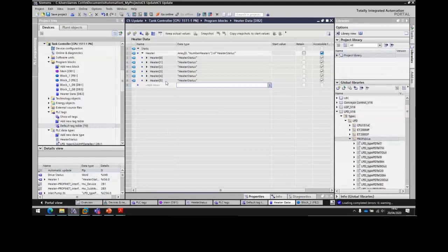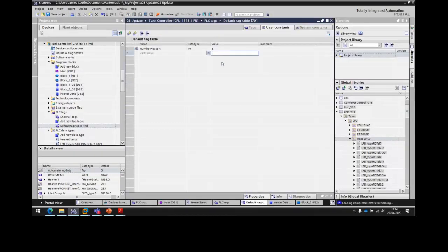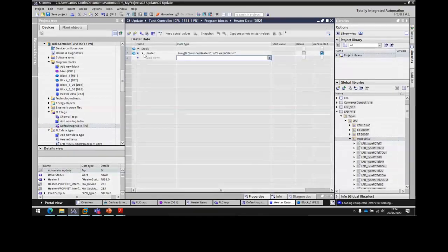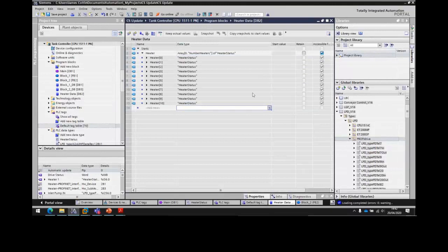So this is a fantastic way also of scaling up and down your applications. Many times you see people define an array which is a buffer for storing information, and then maybe they hit the limit of the controller they're in because the buffers are now too big and the controller's only got a certain amount of memory. Using constants when defining arrays means you can literally come here and tweak the size of the application in a couple of clicks within the user constants, and all the application changes are then happening in the background.